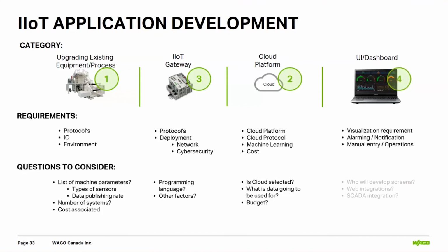And UI and dashboard, obviously we want to figure out what our visualization requirements are, who's looking at it. We can set up alarming and notification, maybe some manual entry for operations. Questions to consider is who's going to develop these screens? Do we need any web integrations, and is there a SCADA integration?